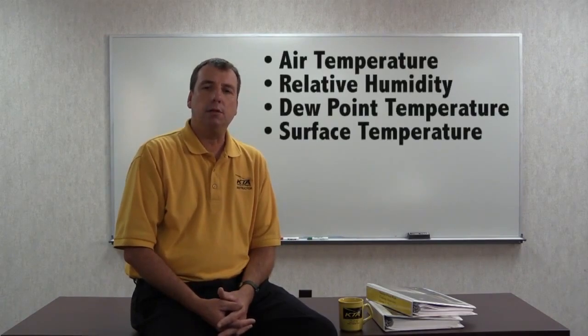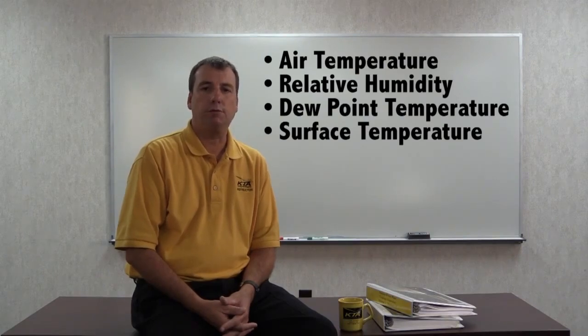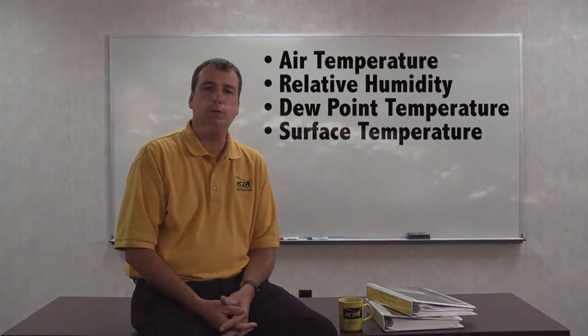There are 3 ambient conditions that are typically measured on an industrial painting project: the air temperature, the relative humidity, and the dew point temperature. Additionally, the surface temperature is measured and recorded, then compared to the dew point temperature to verify that moisture in the air will not condense on the surface. If coating work will be done outdoors, then the wind speed may be monitored.